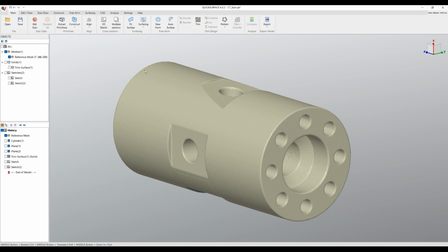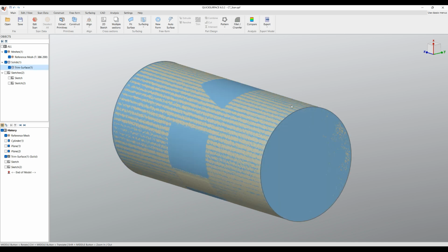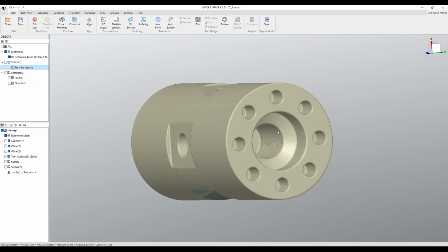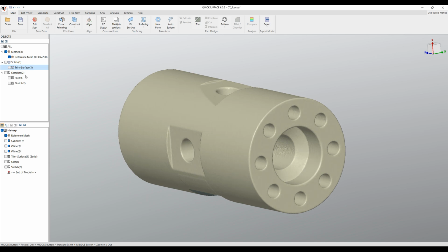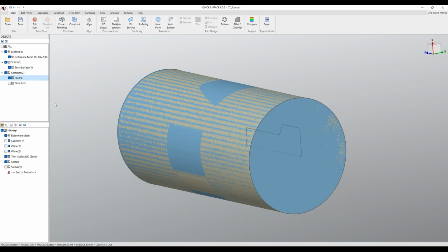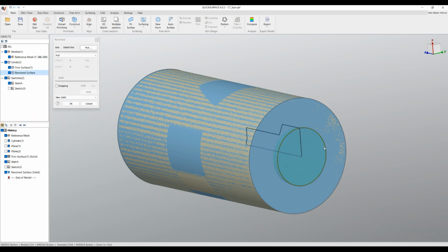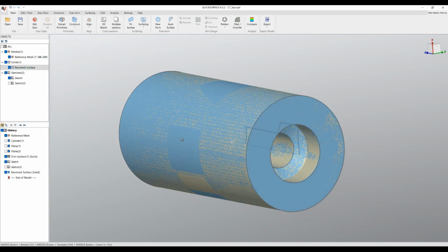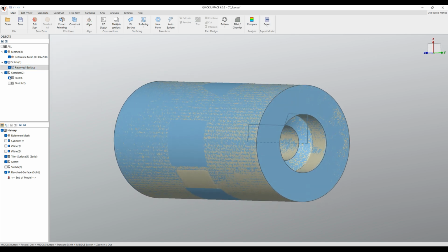When we do solid modeling, for example, I'm building the main body, and what I want to do is have a revolved solid here that cuts, removes material. In the previous version, we just create this revolved shape, and then after that we apply the cut operation. What we introduce here to save time for the user is that you can apply this immediately in the construction of the revolved surface. This saves you time in the feature tree, so you have fewer features to worry about.